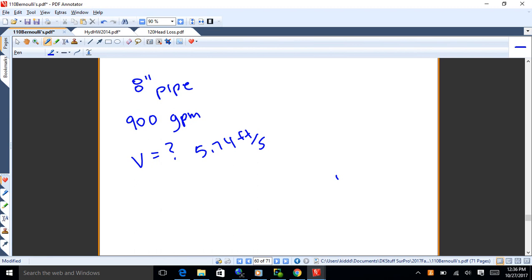Is that always the case? No, I mean, every kind of pipe has a different inside diameter. You could come up with lots of these charts for ductile iron pipe and PVC and for concrete and copper and whatever. I mean, they'd all be different, right? But this is in the ballpark. And that is something I think it's important to understand about hydraulic calculations, is they're in the ballpark too. When I'm doing this stuff, I don't expect to get an exact, right on the dot answer. You know, there's too much variation in pipe sizes and actual elevations and all this kind of stuff. This stuff isn't an exact science, I don't think. Especially what we're about to look at, which is head loss, okay?